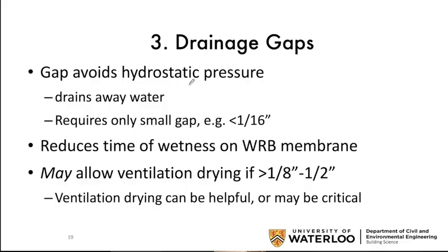That is to relieve any chance of hydrostatic pressure building up by just letting gravity drag the water away. If you stop gravity dragging water away, it builds up pressure. So you just let it go, and it requires very little to do that. There's a bit of research around how big the gap has to be. I'm going to say less than 1/16 of an inch because it's pretty certain it's less than 1/8 of an inch. Probably less than 1/16 of an inch.